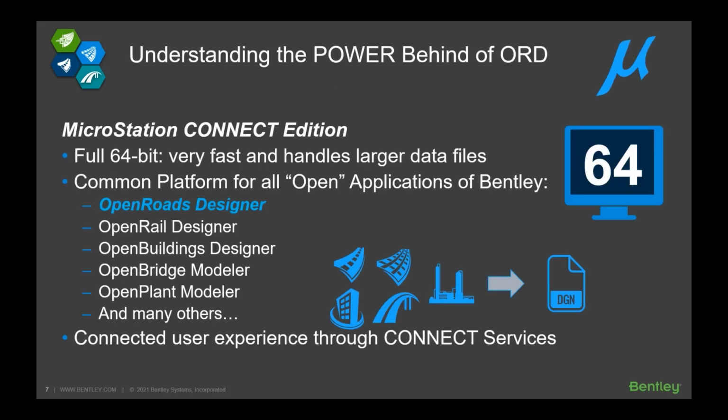So first and foremost, ORD is able to deliver scalable projects mainly because its platform is already powerful enough to sustain medium to big scale projects, which is MicroStation, already in the Connect edition. It utilizes the full 64-bit computing power of your operating system, and ORD leverages numerous MicroStation-based configurations that make it stable in its computing capabilities. Its CAD configurations are the basis of the fundamental civil feature definitions of ORD. You will also later find out that the dynamic drawing production tools of ORD are based on the robust systematic functionalities of MicroStation.